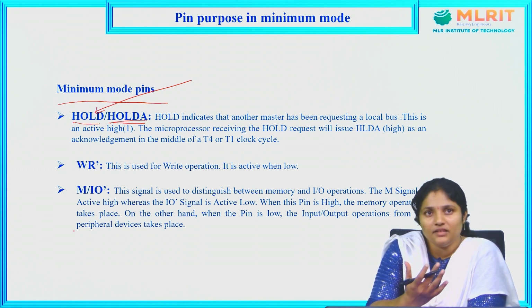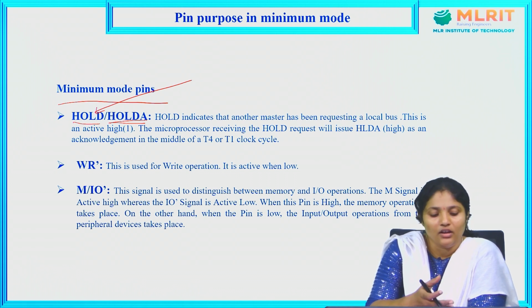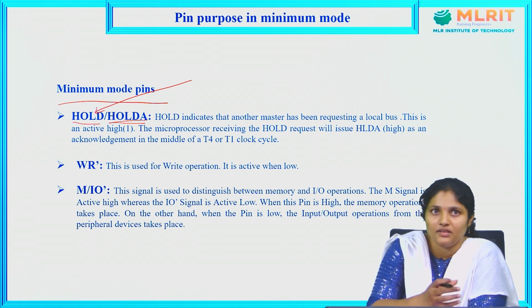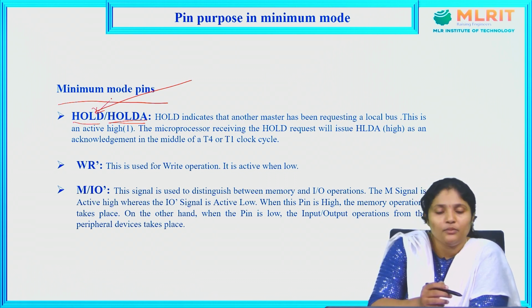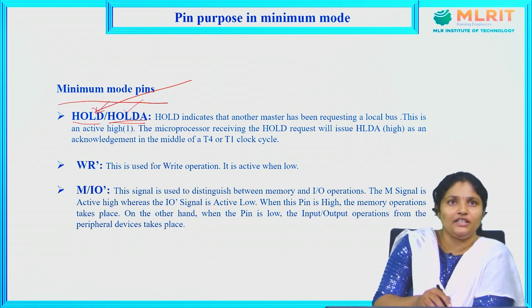If it leaves the system bus, then it will give a hold acknowledgement saying that yes, the system buses are ready, you can access them. If it doesn't allow the system buses, it will also acknowledge through this pin. If other peripheral devices want the system buses, they approach through the HOLD pin and the processor gives the acknowledgement through the HLDA pin.